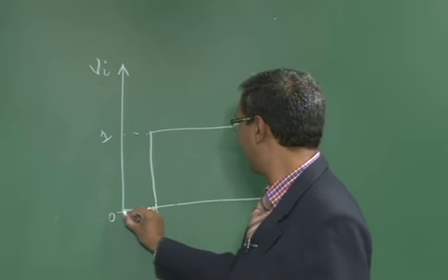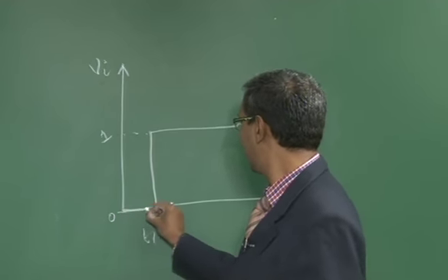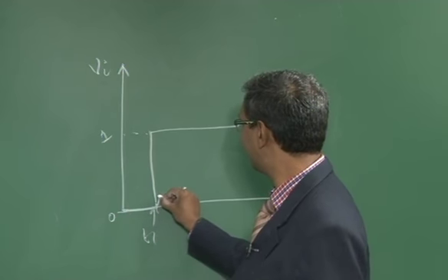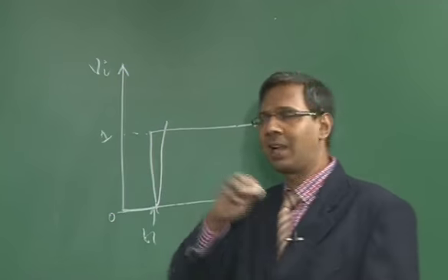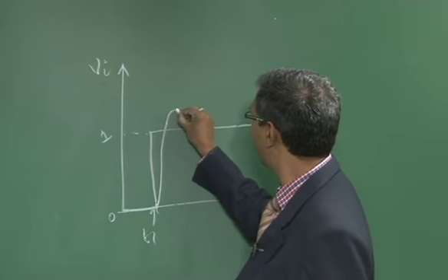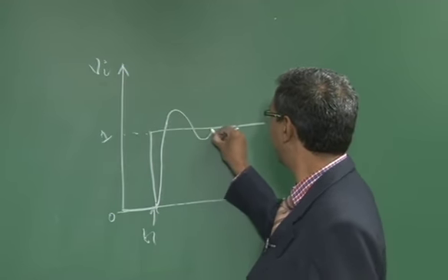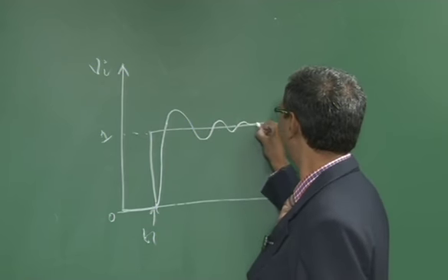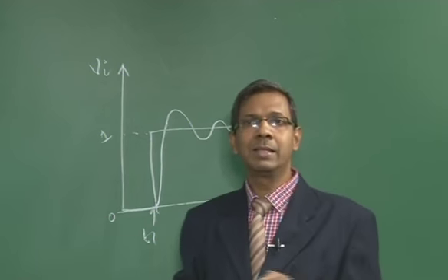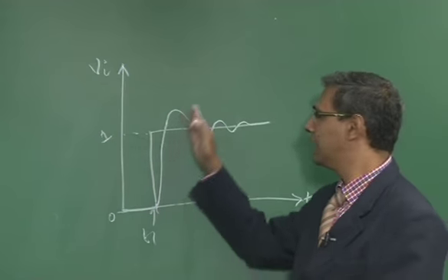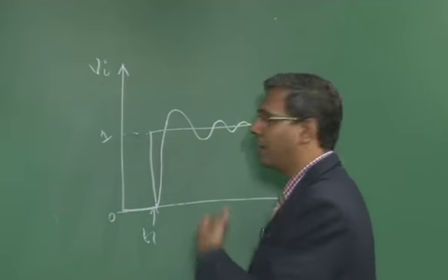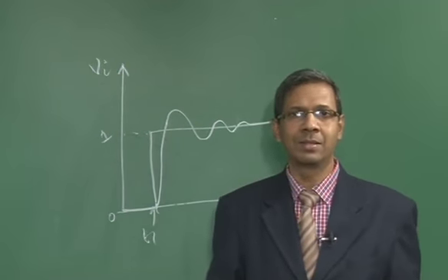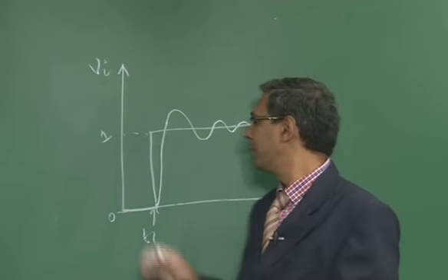So typically what happens is, this particular op amp starts rising and it overshoots, right? It shoots up, it does not settle at 1, it shoots up and again comes down and does a hunting phenomenon, and it eventually settles to 1. This is called the transient behavior of your op amp. Now with this behavior you can analyze many things. First, let us talk of slew rate.